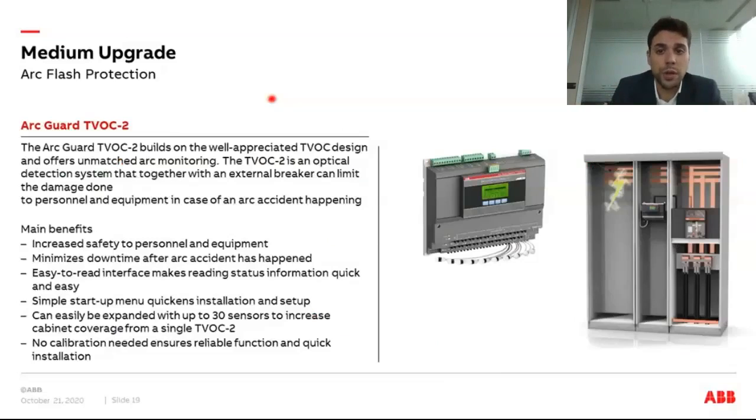We always encourage you to do so at an early stage of the project, on the greenfield installation, in order to prevent the arc faults, but you can also retrofit into the existing equipment, and in less than 50 milliseconds completely disconnect the arc energy.